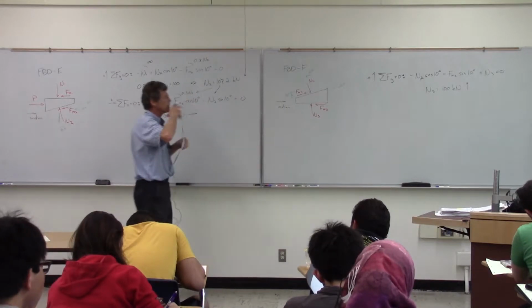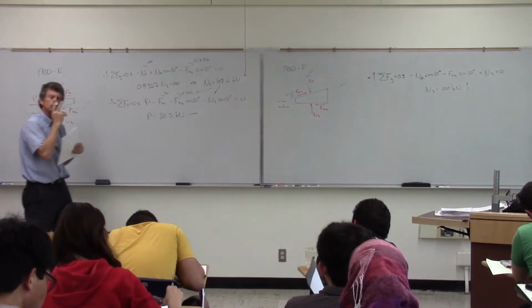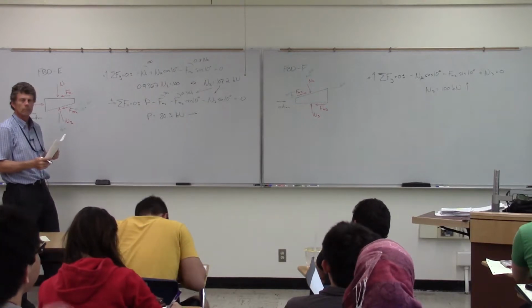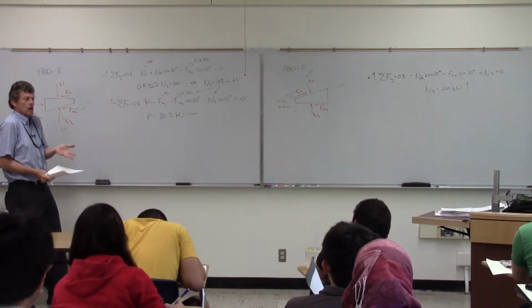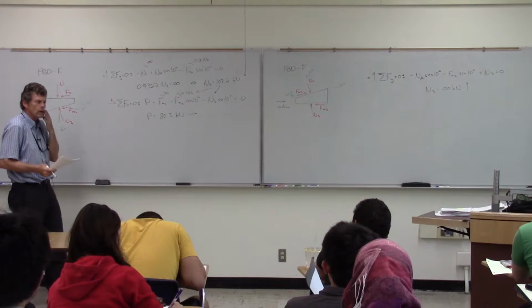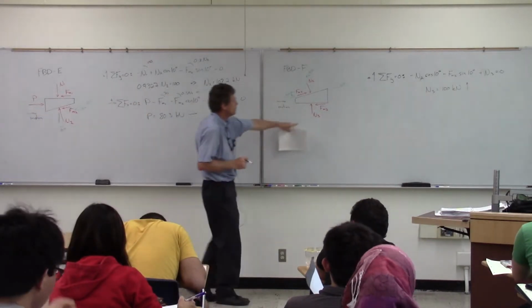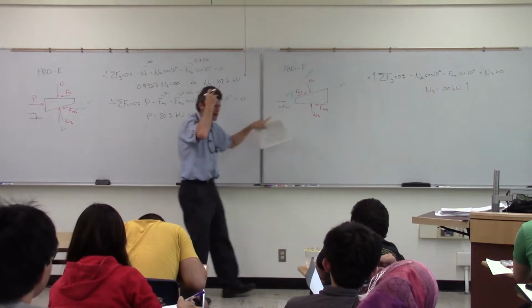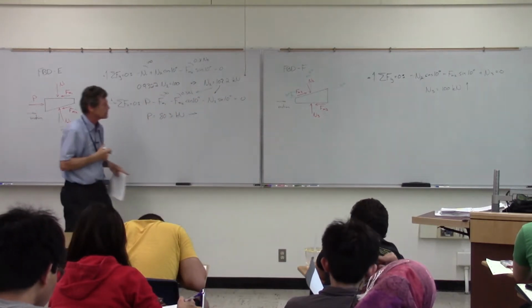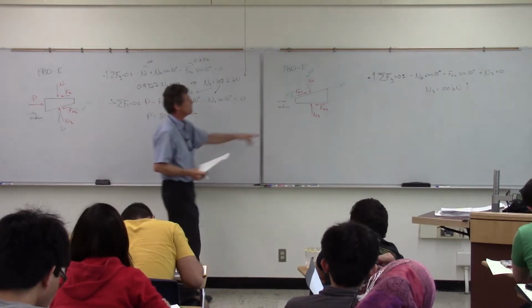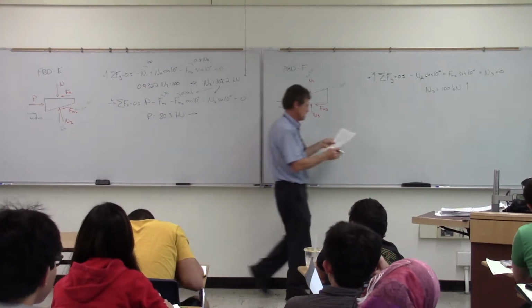Now going back to the point you made there, 100 kilonewtons, does that make sense? Yeah, because the whole system is 100 kilonewtons without the weight of the wedges basically acting on the ground, so we expect to see 100 kilonewtons. So another way of checking yourself, again, I want you to think about checking yourself along the way there. The whole free body diagram should give us 100 kilonewtons for that.